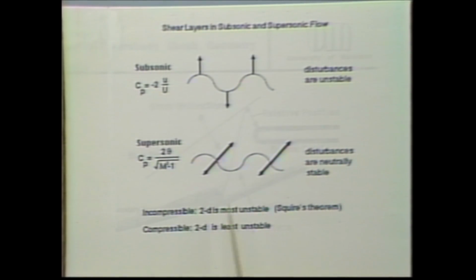You know that from boundary layer theory, one of the theories that's been developed is to look at the way disturbances propagate in a laminar boundary layer. Tollmien-Schlichting theory looks at the propagation, the stability of wave-like disturbances. And I think you can apply a similar argument that as you go to higher Mach numbers, wave-like disturbances in the boundary layer are less unstable. And that, to me, gives you a good physical feel for why boundary layers tend to be more likely to remain laminar at the higher Mach numbers. So it's really the same phenomenon that we see with the fuel mixing. And I thank the individual who brought that to my attention.